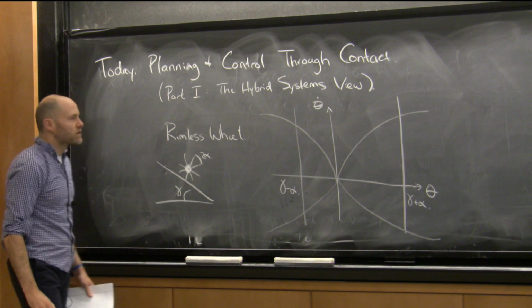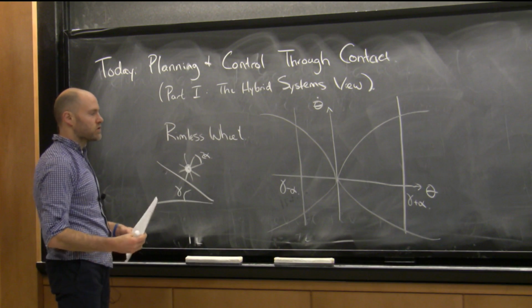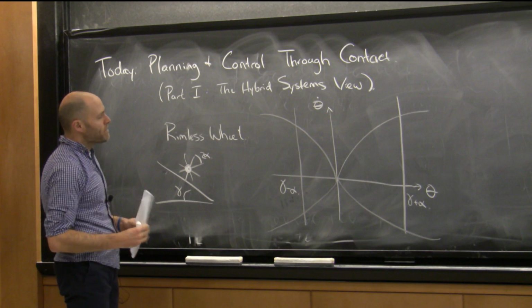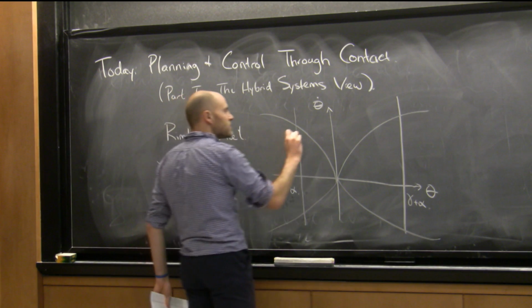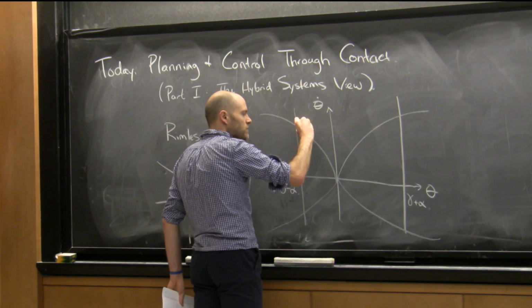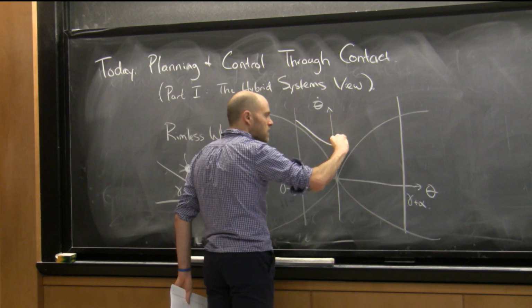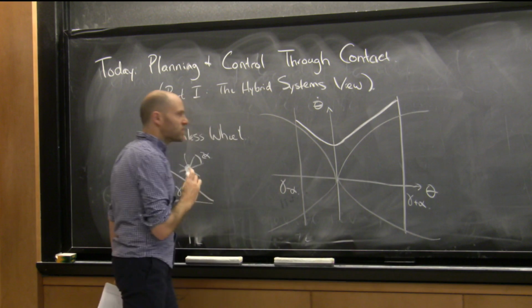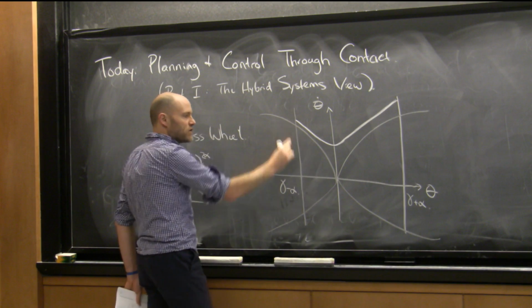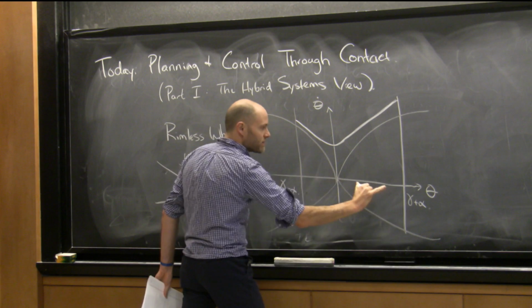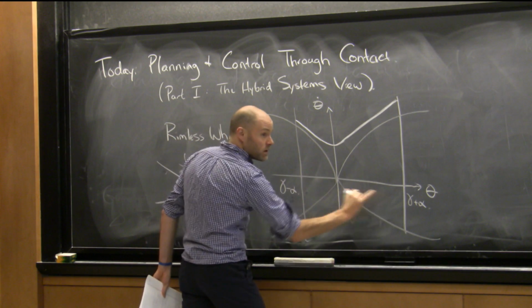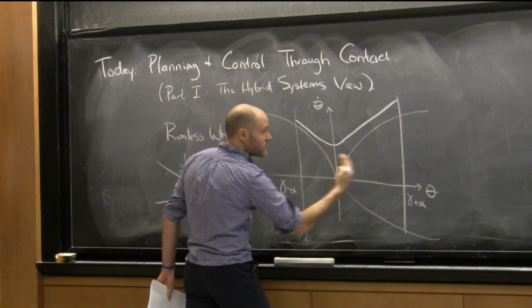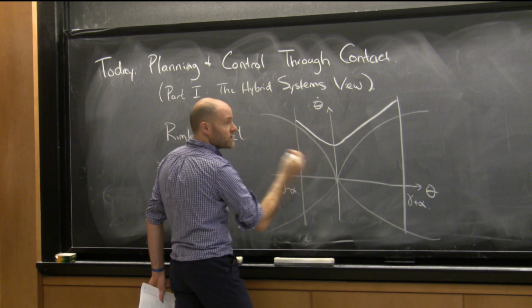And we found, with a little bit of solving equations and writing out the map, that there is a neat place right around here where the rimless wheel goes down, comes back up, but then on impact it loses exactly the same amount of energy that it gained by this asymmetry, by going down the ramp, represented by the fact that this leg of the journey is longer than this leg.